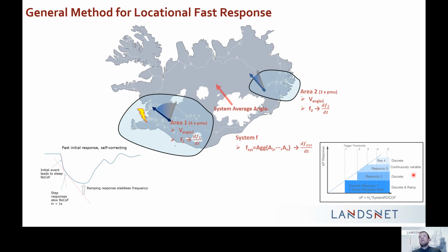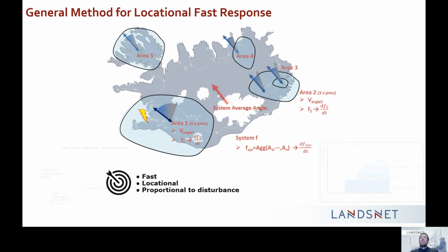And these schemes can adjust really quickly if an island is formed. So it detects if islanding occurs, and then it changes parameter sets to the particular island where the resource is being controlled. Again, that general method allows for a multi-area scheme, so you can add as many schemes as you want.